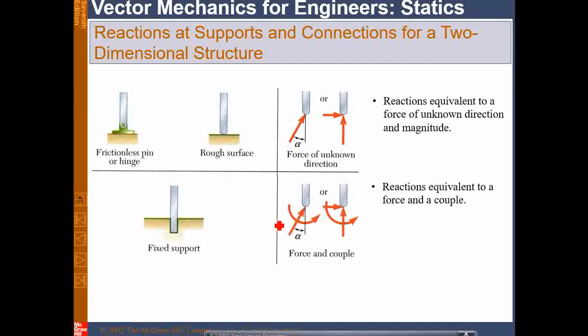Like for example, this is a fixed support. Now here comes one important thing. As this is a kind of fixed support, we will have the force components also along the x, which is restricted, so X reaction. Y is also restricted, so Y reaction. And once I put the load, this will also create a moment. This will create a force couple moment. So due to that, we actually have to put the moment sign here also. We have to find the moments in this case.